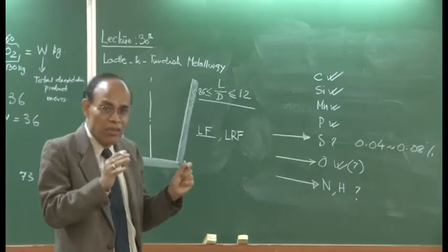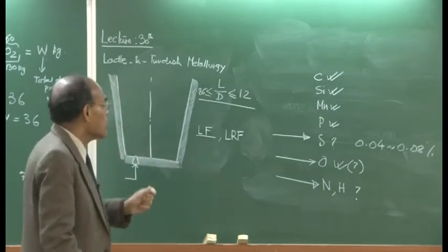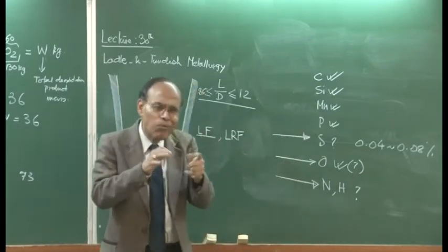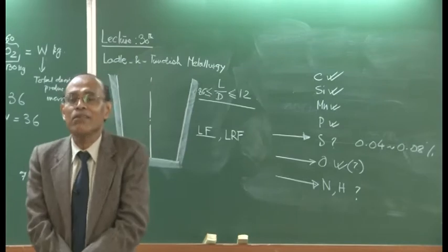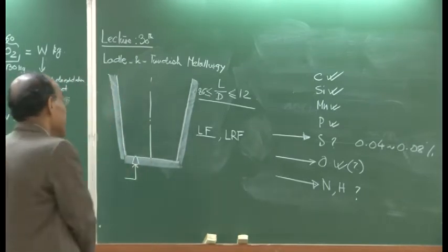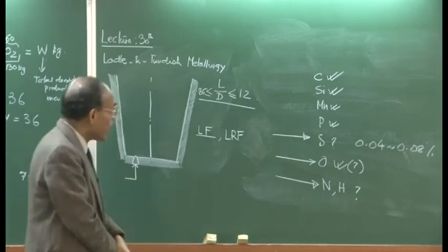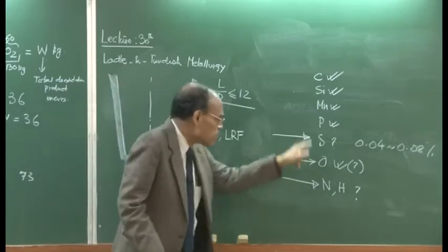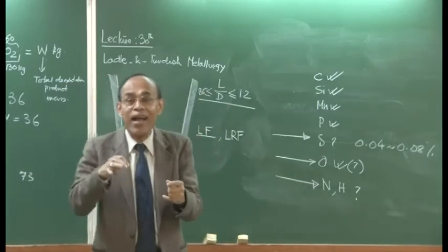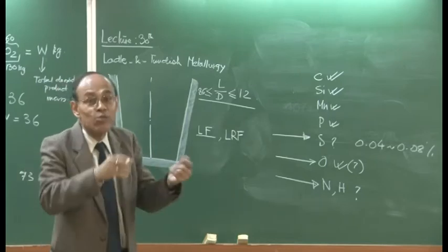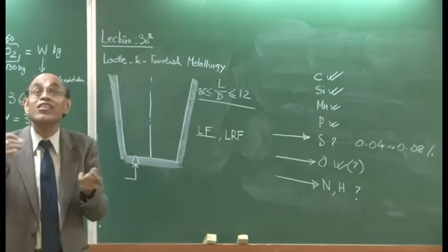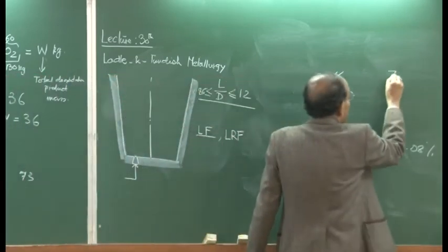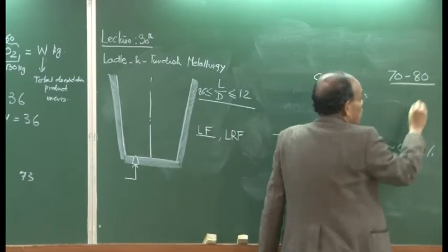So, there are a lot of processes which are still left, because steel at this particular step, although it fulfills composition grossly, is not what we would like to deliver to the customer, or maybe it is not at the level desired by the customer. So, it requires further refining. All these things, adjustment of temperature, adjustment of composition and adjustment of cleanliness, will require some time. How much? This could be as much as the duration of the primary steel making process, or longer than that, 70 to 80 minutes more of processing time will be necessary.